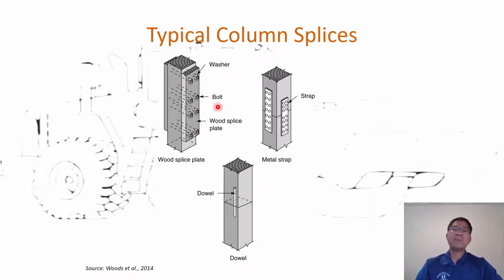But if we have moment or shear, the connection for the column in wood can be more sophisticated. As you can see here, use straps, bolts, and washers, and then wood supply plates, all of that to improve the ability to withstand moment or shear at that point, compared to the lower connection, which tends to sustain only the central load for the column in there.